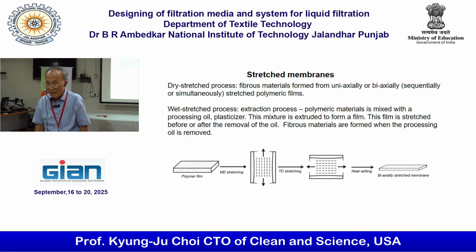So isopar something. So oil. The other important thing is the raw material you have to store at room temperature. No, lower than room temperature, because otherwise it crystallizes quickly. So storage has to be less than 20. No. Important temperature is 19 degrees. 19 degrees is important. So it has to be lower than 19 degrees. Storage is the same thing.